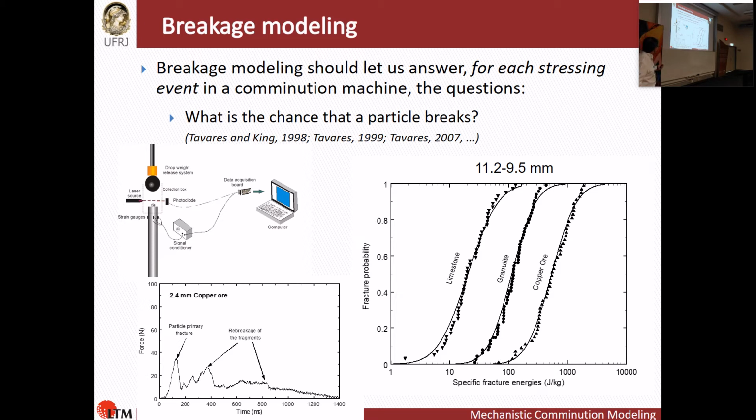It is a very tedious test, of course, but the outcome is very enlightening, because you can look at this very narrow size range and see that each of those is a different particle containing the same size and the same composition. And you can see the amount of energy that's required to break each of those particles. Even for the same material, it's an order or two orders of magnitude between the toughest and the weakest. So variability is part of our business.